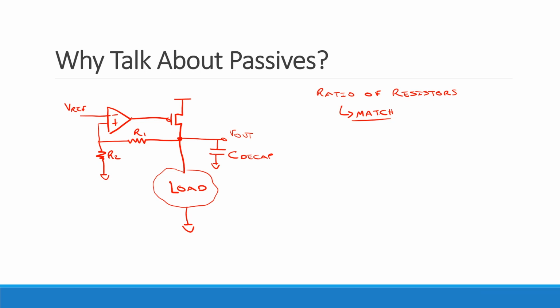You're choosing the values of these things. How would you choose, or roughly what would you want to set those values to? Large. Why do you want them large? The actual current I want is over here. Any current that I've got flowing over there is just wasted in some sense, right? So generally speaking, I want those resistors to actually be pretty large.